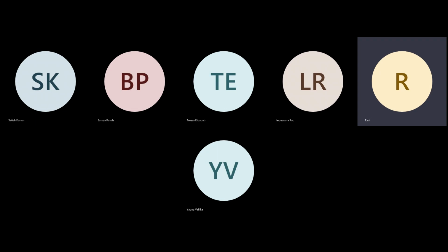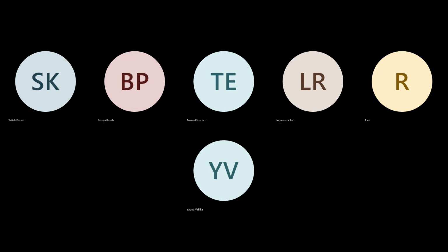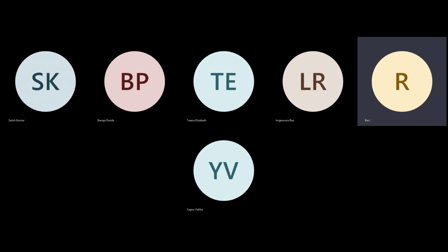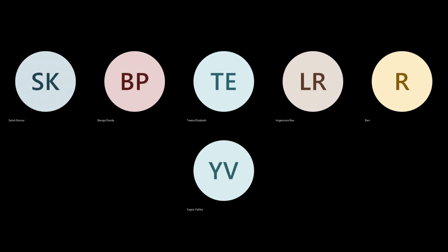But if you have site rows, which means circuit row height, standard cell height, that are different, more than, like, 1.5 or 1.25 or something, not a multiple, then you'll have to create a separate voltage island so that the cells can sit. Because otherwise, what will happen? It's on the site row that you create your VDD and VSS. If you have 1.38, then another 0.5 will go like this, and it won't be able to place. It will be a mess. You cannot do it.